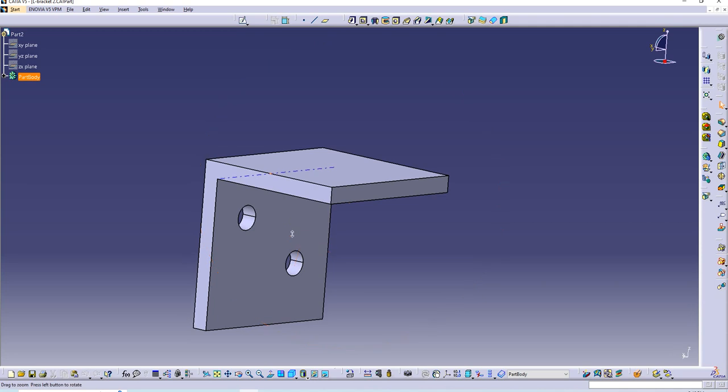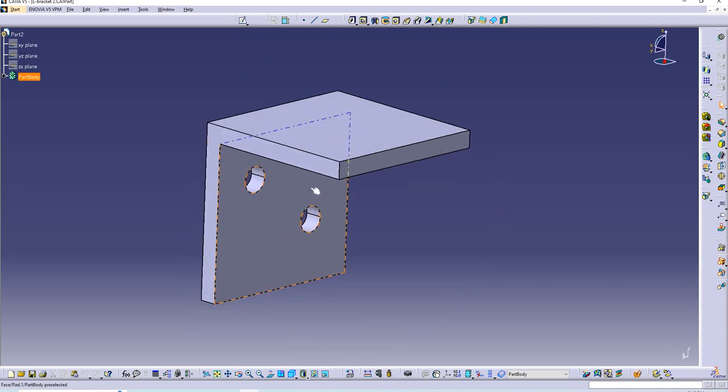It is a stiffener that will support the load that is being exerted on the surface, and by having this stiffener, it distributes the load through the stiffener and into this other part, so that the bending of this plate will be reduced compared to without the stiffener. So we'll see how the analysis goes after this.